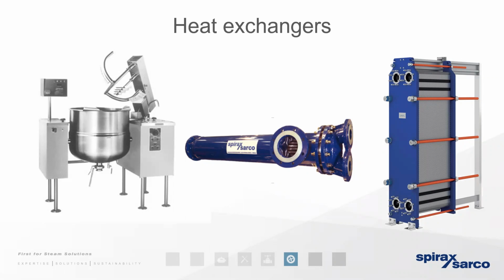So it bears mentioning that steam can be used for direct injection purposes. That's where the steam enters the atmosphere or the process, and therefore the condensate does too. Both the latent heat and the sensible heat go into that atmosphere or process. So in those cases, there simply isn't going to be any condensate to be removed anyway.